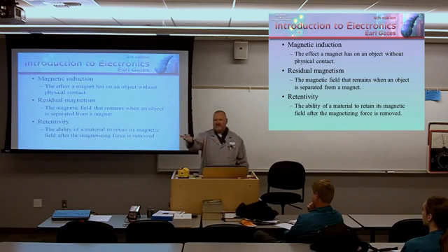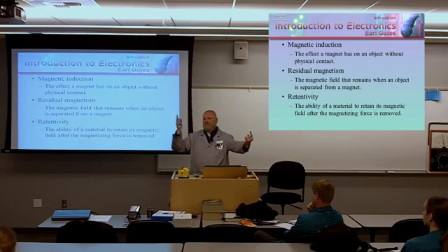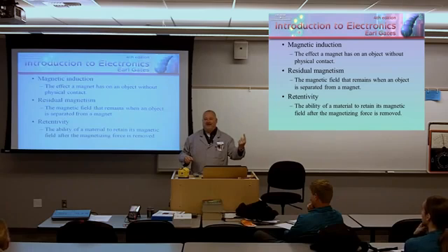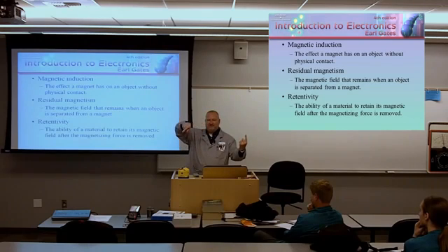What they would typically do is have a circular scan radar, so when they stick up a periscope, all of a sudden they get a blip, blip. If it's a good radar operator, that's all it takes, two blips, and then he'll shut the radar down. So they'll continue to fly, and then he'll go to a sector scan. Okay, so from a circular scan, blip, blip, then he'll shut it off. Then he knows where he's looking because he saw it on the radar screen. He'll go to a sector scan, right? A sector scan is back and forth like this.